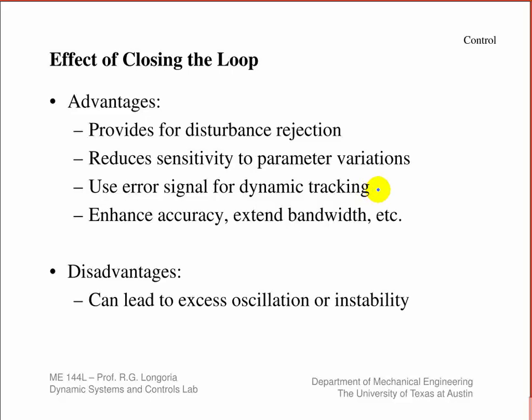We usually talk about two kinds of controllers of this type. Usually you have something that's called a regulator. And usually a regulator refers to, you want to keep something at a certain spot. So let's say we wanted to put the needle at a certain position and leave it there. And so you're telling it go to 20 degrees and stay at 20 degrees, and no matter what disturbances it has, the controller's fighting to keep it there, right? That's a regulator. Keep it at 0, put it at a certain position, hold it there. A cruise control is like a speed regulator, right? You're trying to stay at that constant speed.